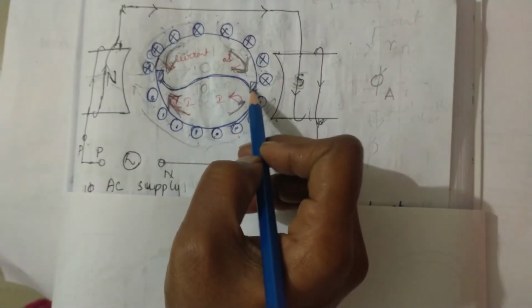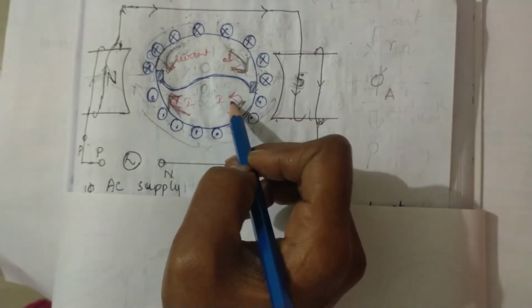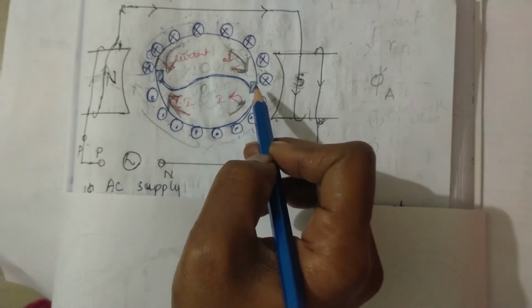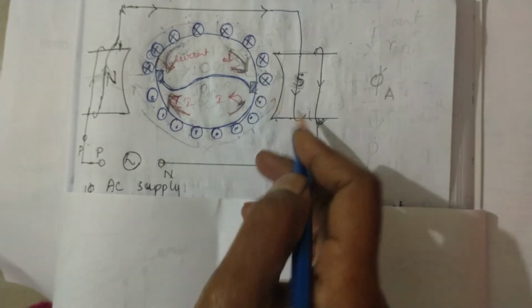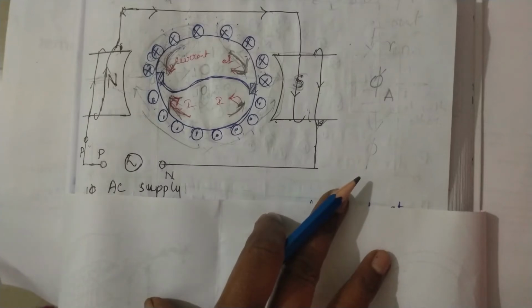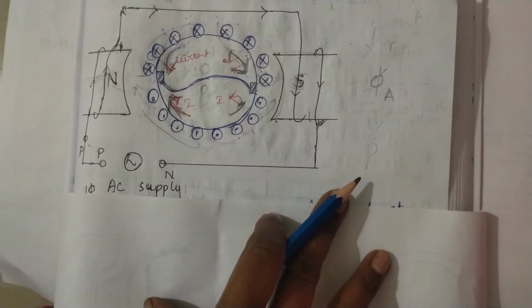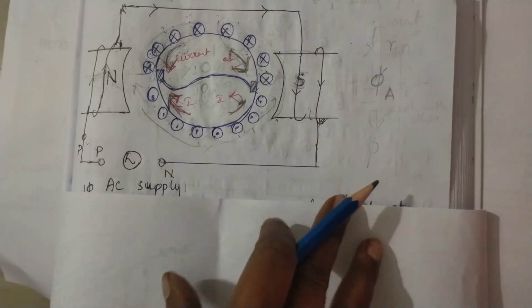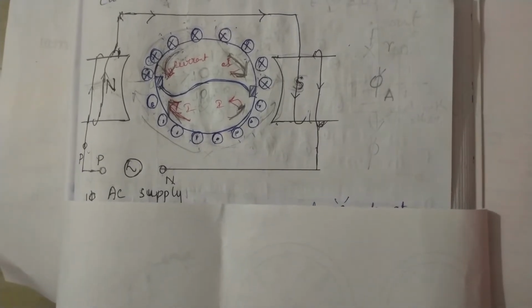Here also in this brush side, these two arrows are opposing with each other, that is net torque will be 0. Hence we can say at alpha equal to 0 degree, if we are keeping our brush position at the same collinear position, collinear axis, then the motor will not rotate. Okay, it will be in stationary condition only.